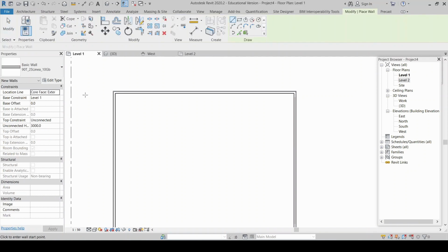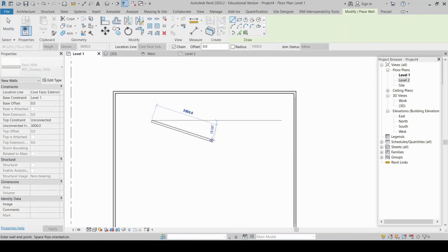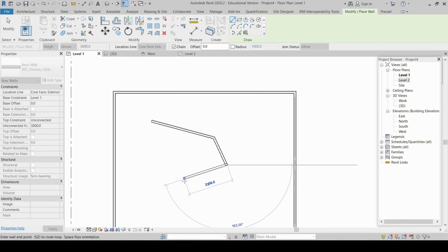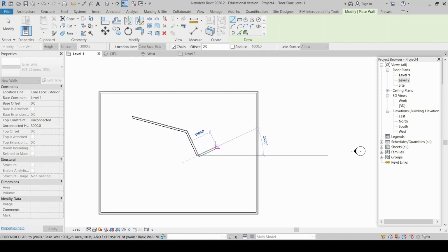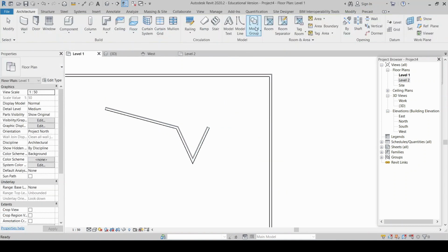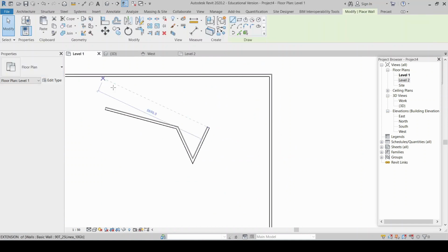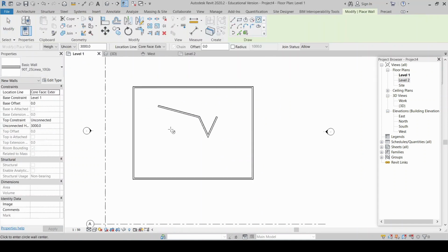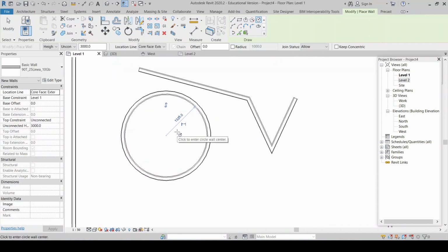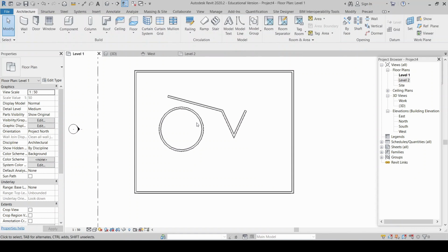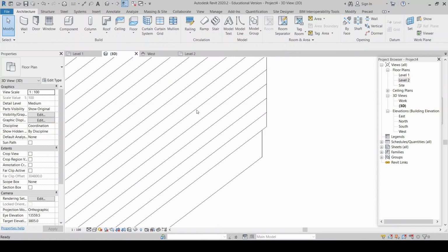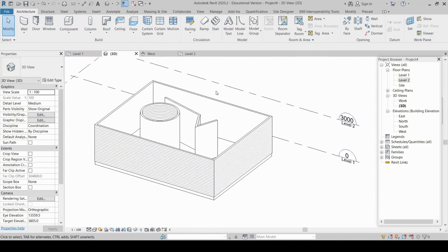We use the wall tool, we pick a wall type, and we draw the shape we want. And we can have complicated shapes, we can define circles. If we really want a circular wall, we can do that. Revit will happily do that. We can do arcs, we can do all sorts of things. And we can connect walls together and change their types. So the wall tool is very simple. All we're doing is generating lines that represent the line of the wall.